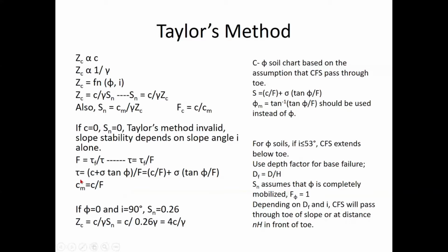Again, I know the factor of safety in terms of mobilized cohesion, so I am just representing that here again. Okay, Cm is equal to C by F. I'm just refreshing all these expressions that we have seen previously, because we will be using these for the problems that we are going to do now.